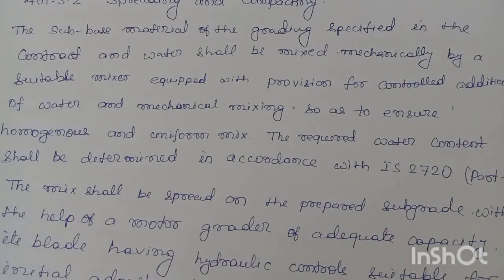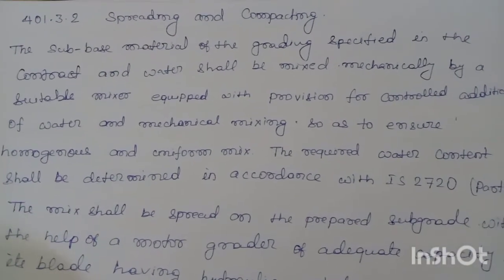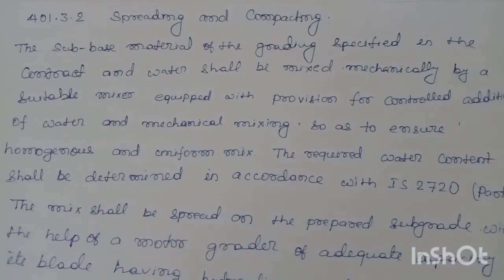401.3.2 Spreading and compacting. The subbase material of the grading specified in the contract and water shall be mixed mechanically by a suitable mixer equipped with provision for controlled addition of water and mechanical mixing so as to ensure homogeneous and uniform mix.